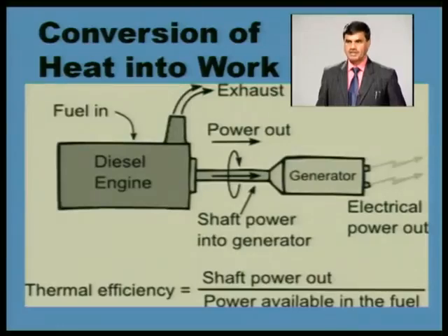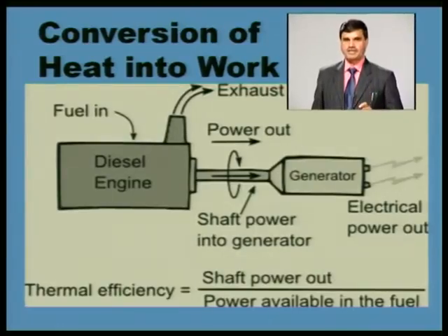I am giving an example of conversion of heat into work: the diesel engine, where the fuel is diesel. It was invented by the scientist Diesel somewhere around 1896, where the heat addition process, or combustion of fuel, is very special. When heat is being added into the combustion chamber, more or less the pressure remains constant, hypothetically. So, the heat addition process in the case of a diesel engine is at constant pressure.